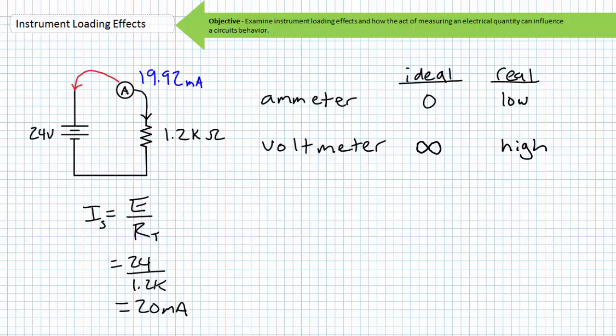Ammeters have low resistance. Voltmeters have high resistance. Ideally, a low resistance ammeter placed in series with a component it is intending to measure current through won't unnecessarily present additional opposition to a source. Ideally, a high resistance voltmeter placed in parallel with a component it is intended to measure voltage across won't draw additional current. Quality ammeters and voltmeters do affect circuit properties, but they don't affect it much. Poorly made equipment affects circuit properties, and sometimes these effects are noticeable.